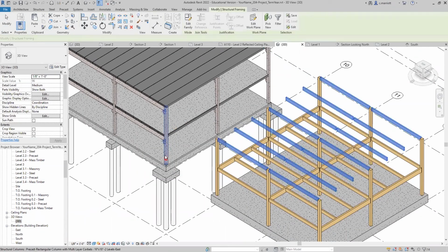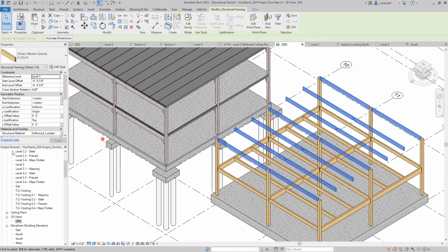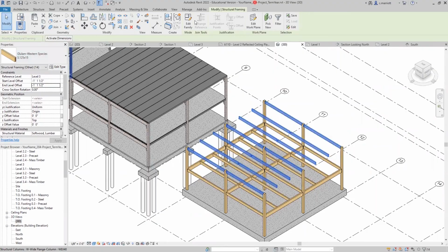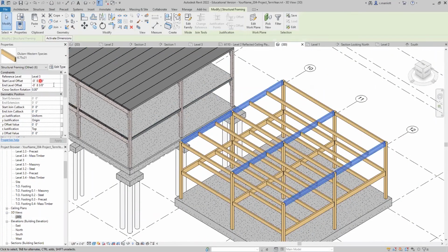You can see they're kind of floating too high. I'm going to move them all so that they are lower, and you can see I've only got the beams here. Remember the height that we used for that was minus 1 foot 1.5. This is relative to the third level. So now they're in the proper location, and I'll do the same thing with the girders. Up there, and now I'm going to change those to minus 1, 5.